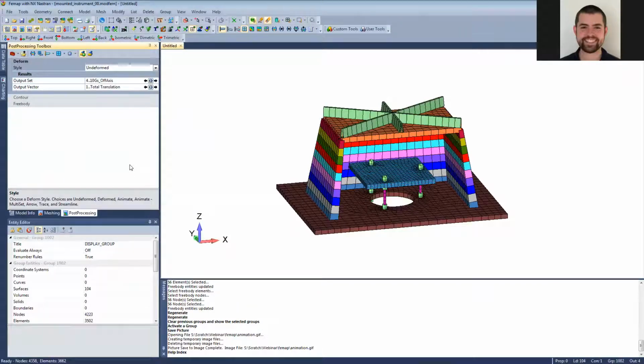And then Andy, when you export a GIF, does it take your current animation settings in terms of frames and delay and all of that? Yeah, it will consider those current animation settings. So if you had adjusted the default delay and frame settings to either speed it up or slow it down, that should translate to the GIF that you export. And that's definitely something to be sure to test out before you take that GIF to a customer presentation, for instance. But those settings should translate to the exported GIF, yes.